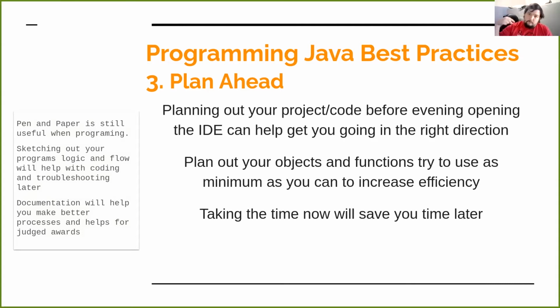So I need to receive input, power on motor, extend arm until X point. Once it's at X point, then I need to close servo, then I need to retract arm, right? So I press the A button and it does those 3 actions. Now I have a clear idea, I've written it out, of what I need to write my code to do. You know, and then that is going to probably get simplified to a single function. But within that function, what does that look like?